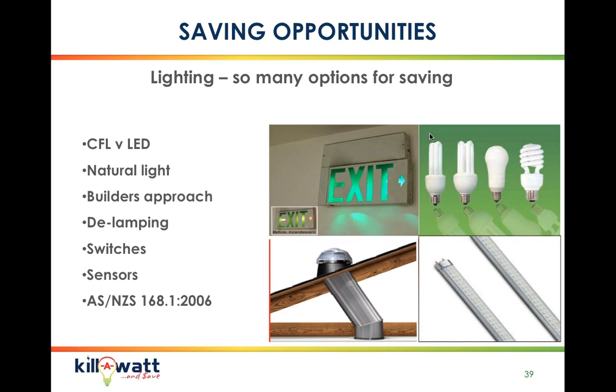Okay, lighting. Lighting is a big one. There's been a lot of advancements. People think that compact fluoros are energy efficient. Compact fluoro technology has been out just over 24 years, and there hasn't been many changes. There's been a few changes in how the switching and the starting happens, but essentially they're still the same equipment. The latest advancement has been LED, which is now becoming very cost effective, but needs to be looked at on a case-by-case basis.